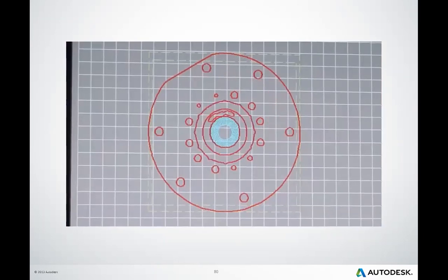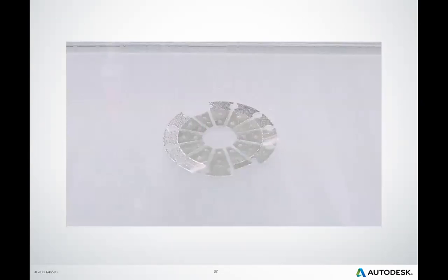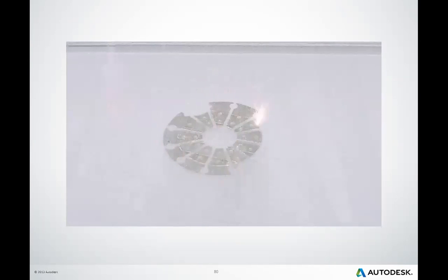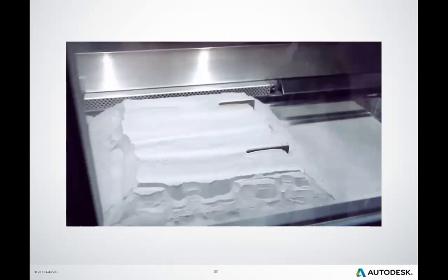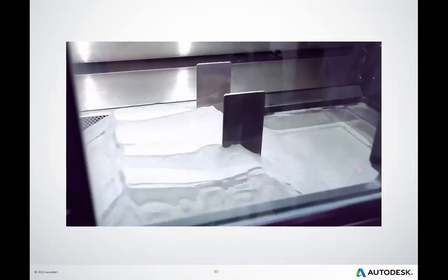While building tools, we combine traditional subtractive methods of production with additive manufacturing. For the last 4 years, we've been developing selective laser melting technology in the context of conformal cooling designs. Being able to use conformal cooling for our production purposes has been a huge asset, as it enabled us to learn the technology and understand its strengths and pitfalls. Cycle time is money. This is particularly visible in the case of high volume production, where reducing cycle times by a fraction of a second translates into viable profits.